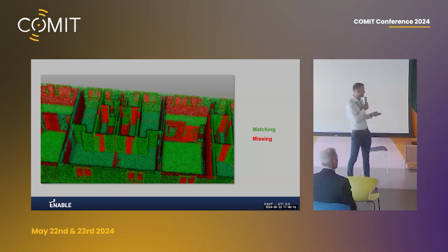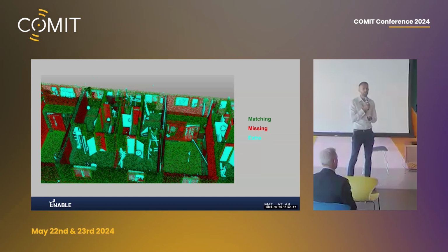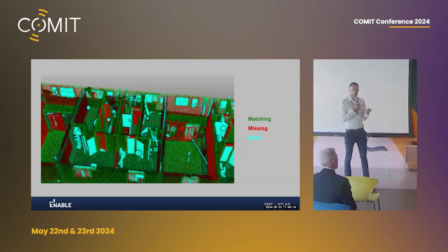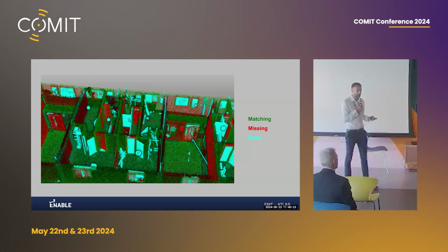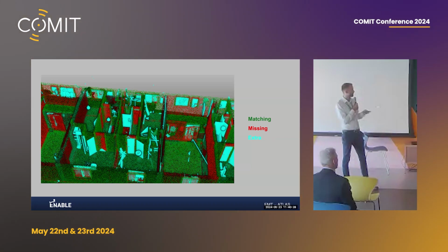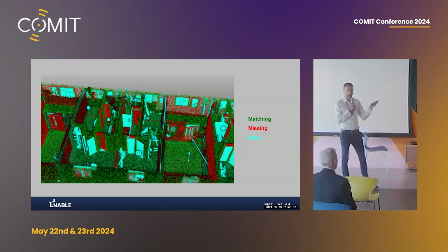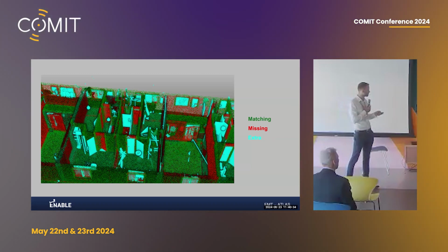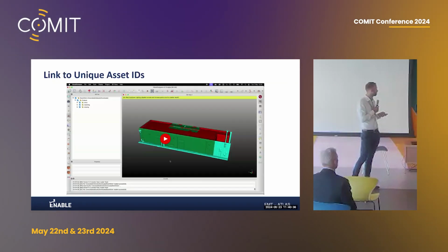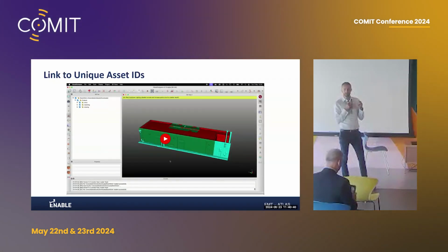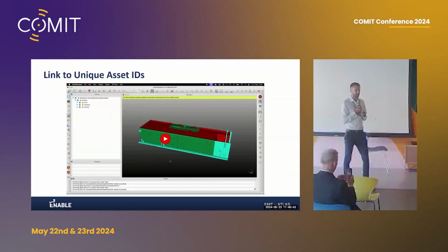We can then take it to the next level when we start to then overlay the extra items. So during a construction project, you'll have a lot of extra stuff in a point cloud scan. Some of this will be temporary work, so you're not particularly worried about that. You can toggle it off. But some of it will be additional items which have been installed and for whatever reason weren't modeled. Things like your electrical boxes and that cabinet above the stairs, for example. But again, as I mentioned earlier, we don't want it just to be generic points. We need to actually provide some context here.